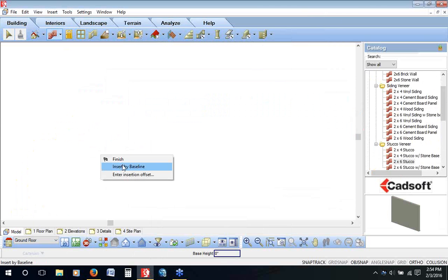This tool, as you're going to see, will draw a single line diagram. I'm only going to see one single line being drawn. And I'm going to be able to type exact dimensions of how long that one line is. When I'm done drawing all the lines that outline the footprint of my exterior walls, I can then designate that line is either the very outside edge of my stucco, or it's the very inside edge of my drywall, or it's the center line of my stud. So depending on the dimensions that you want to pull from it, this helps you to use those very accurately. Let me show you.